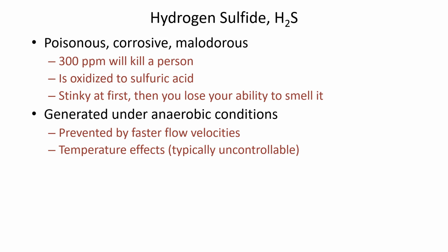When there is sulfur in wastewater that is anoxic, the bacteria that break down BOD in the absence of oxygen can transform the sulfur into hydrogen sulfide gas. And it's very dangerous. As low as 300 parts per million could potentially kill a person if the exposure duration was long enough. Higher concentrations are dangerous in shorter time periods.